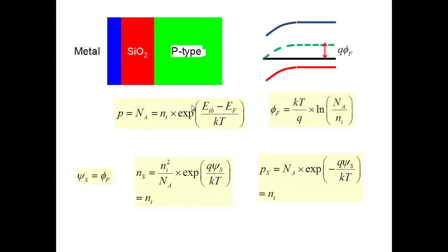How will the energy band diagram look like? And Ns equal to Na is what condition? Electron density at the surface has become equal to Na. So that's the condition for threshold. Okay, so this is very important. This is the condition for threshold voltage. At threshold, I have this one, Ns equal to Na. So let's draw the energy diagram quickly.